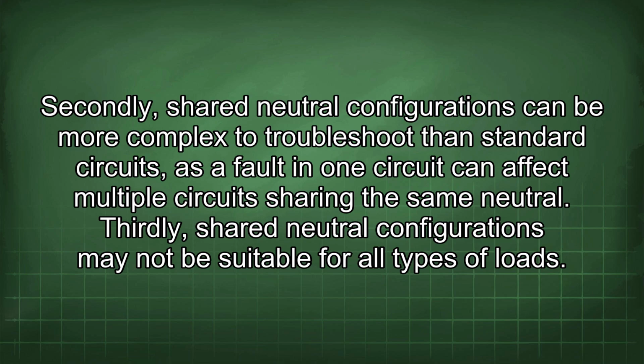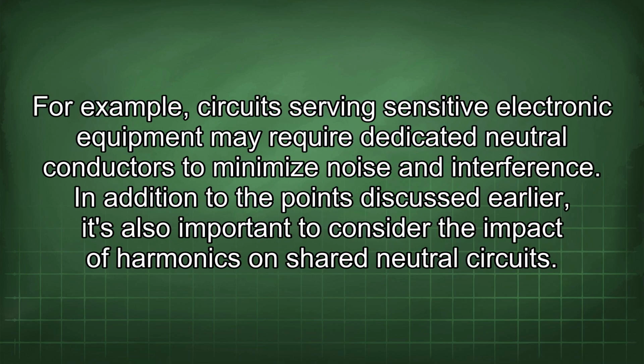Secondly, shared neutral configurations can be more complex to troubleshoot than standard circuits, as a fault in one circuit can affect multiple circuits sharing the same neutral. Thirdly, shared neutral configurations may not be suitable for all types of loads. For example, circuits serving sensitive electronic equipment may require dedicated neutral conductors to minimize noise and interference.